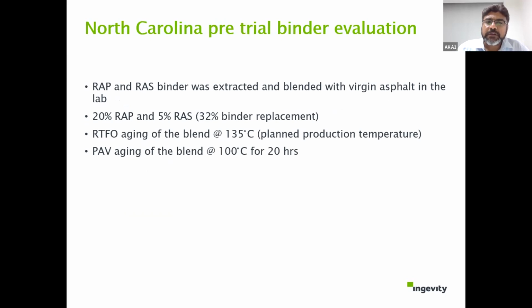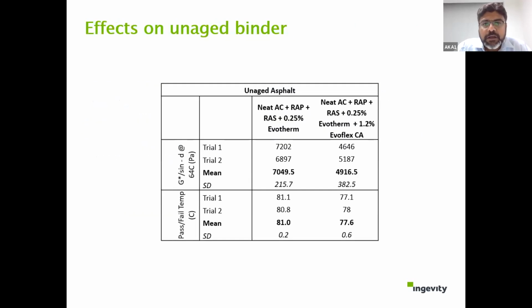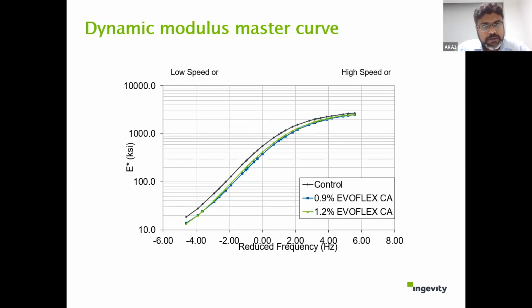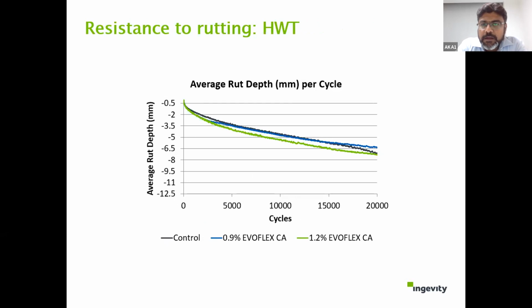Again, another project with different combinations. These are the properties, again using warm mix and warm mix plus rejuvenator. I'll be sharing this; these numbers will be a repetition of those tests. So the modulus values, your typical dynamic modulus that we do against control sections. Rut depths.